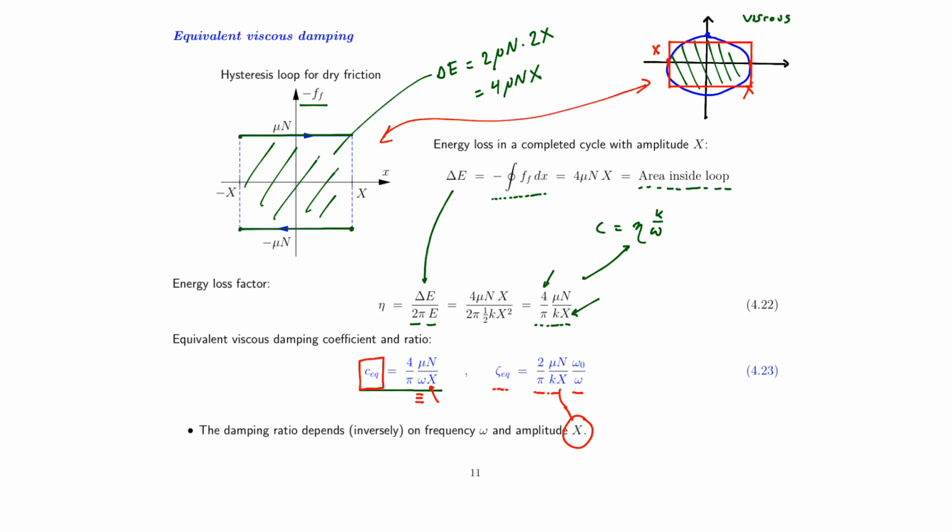So for the viscous coefficient we have larger maximum forces than we have for the friction damper, simply because we have parts that should even out to obtain the same area within the loops. So therefore, if you apply a viscous damping model that is equivalent to the friction damper model, you will encounter a slight overshoot of the associated damping force, Fd.